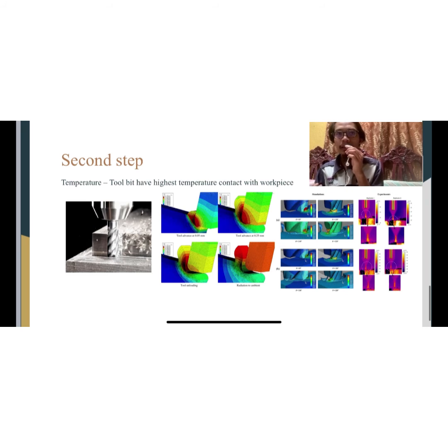The temperature core at the tool tip is very small, usually around 0.5 to 2 mm, depending on the parameters, which is where the maximum temperature is produced. To conclude, the temperature data acquisition method is not very useful for a tool condition monitoring system in manufacturing production.